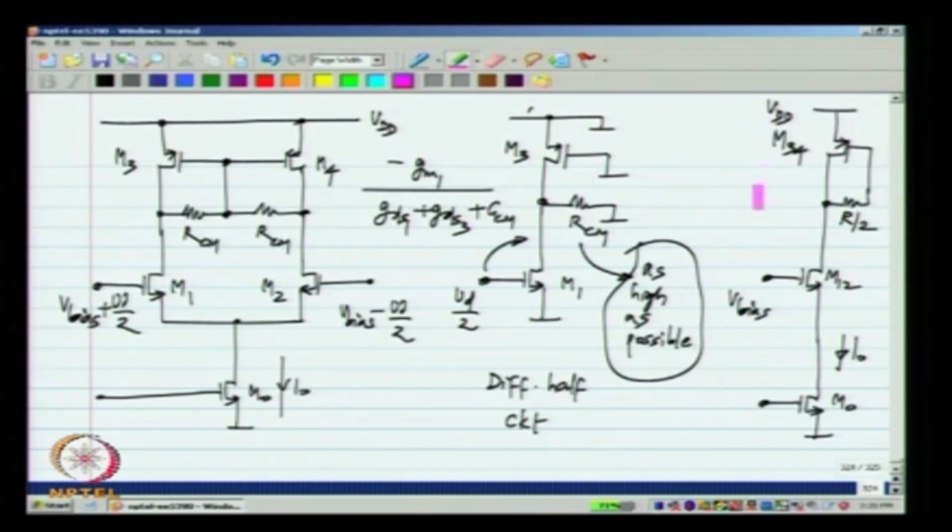So, the goal of the common mode feedback circuitry can also be thought of as providing a load resistance which is very low for common mode and very high for differential mode. Ideally, the common mode feedback circuit should not affect the differential mode circuit at all, but in reality it does to some extent. As we see here, it presents a load resistance R. In the next lecture, we will look at different kinds of common mode feedback detectors and look at some choices which will not affect the differential picture and consequently will not affect the differential gain.